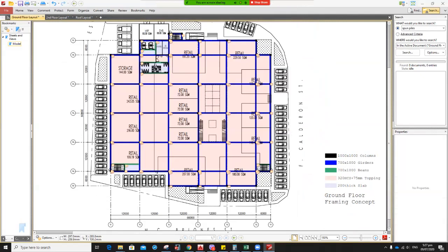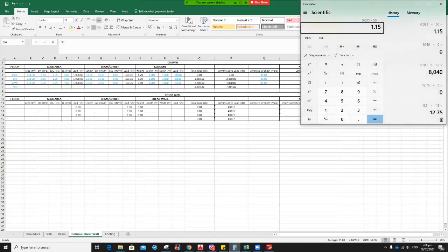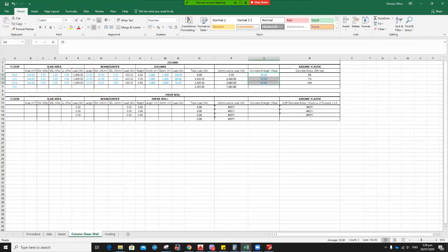So as mentioned, this is just the preliminary sizing or the concept sizing. Okay. Now, once you already finish the sizing, at least we already have defined the concrete strength of the column. So we can now define the minimum concrete strength of the beams, which will be 35 over 1.4 or 4,000 psi. Okay. So we can use 4,000 psi for the beams and girders and the slabs.